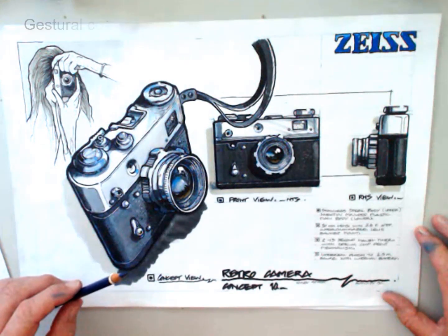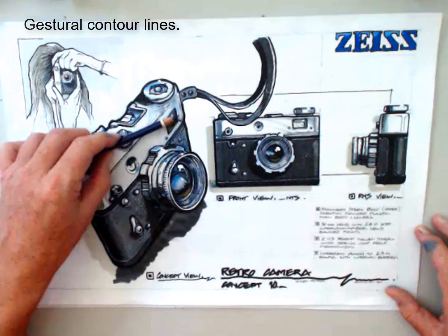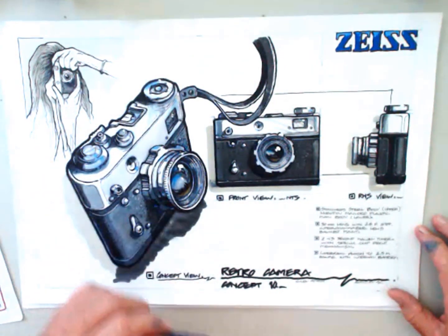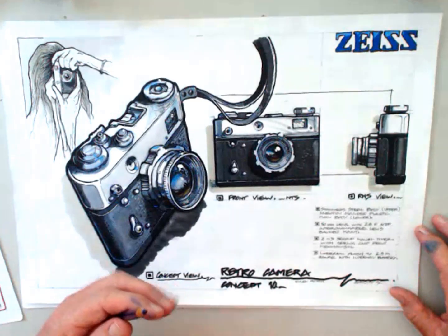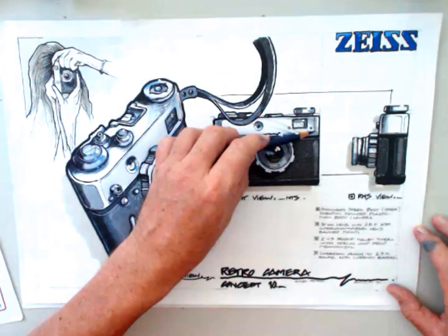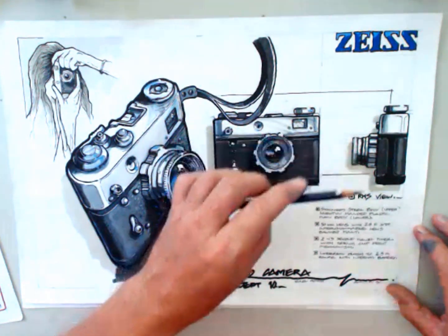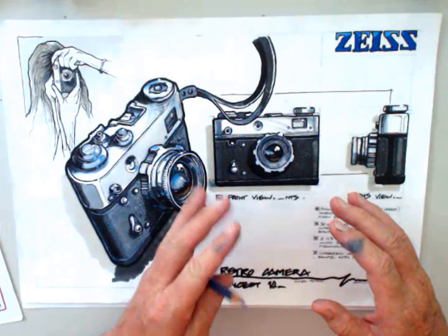And then occasionally there's what's referred to as gestural contour lines. Gestural contour lines convey something about the surface properties of the material. They might be a reflection or a surface blemish or just a highlight, but you can see that these lines here show something about the curvature of the object, even though they're not a hard edge line. So they're particularly useful when you have a curved surface.